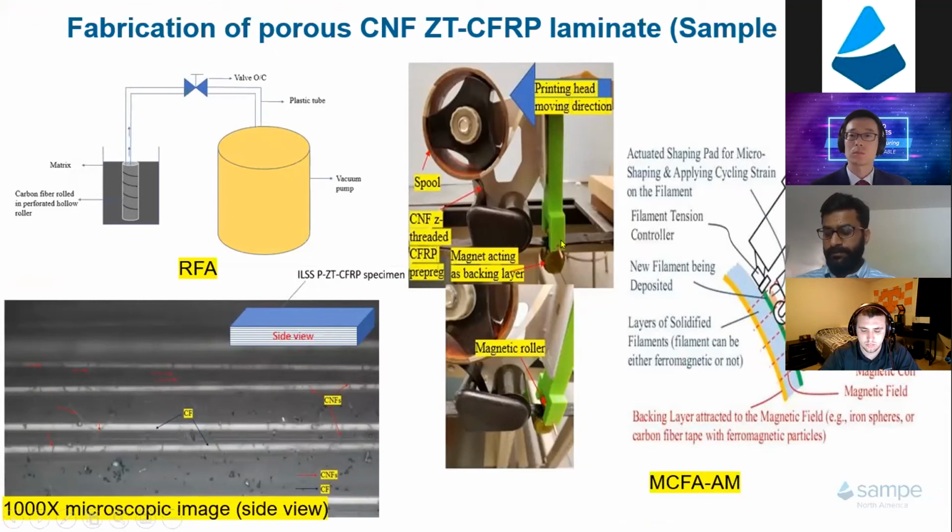We have a magnet on the top roller, and another magnet under the bottom steel roller. The carbon fiber pre-preg feeds between, and meanwhile you have hot air blowing on it, so it cures within 45 seconds when it rolls through. So we control the rolling speed, the temperature, and the compaction force, so you can reach the certain thickness or carbon fiber volume fraction you want.